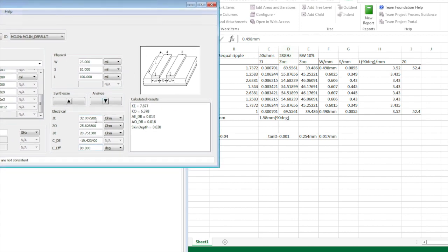And we find that for the impedance when it works at even mode, it shall be 69.5. So we just settle down 69.55, and we better change it to millimeter, since when it works at odd mode, it is around 39.5. So we set down 39.5.